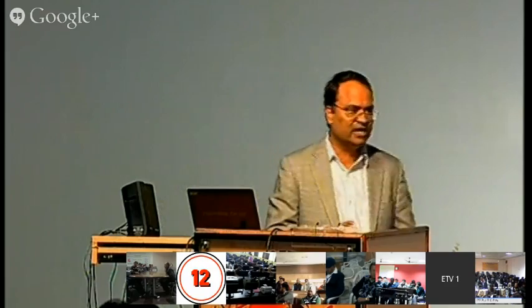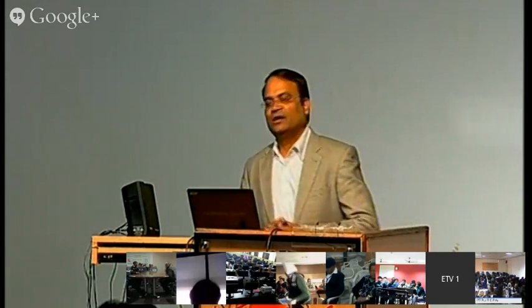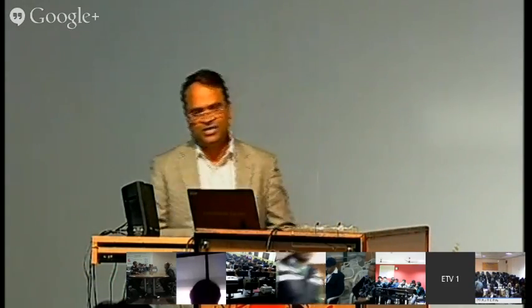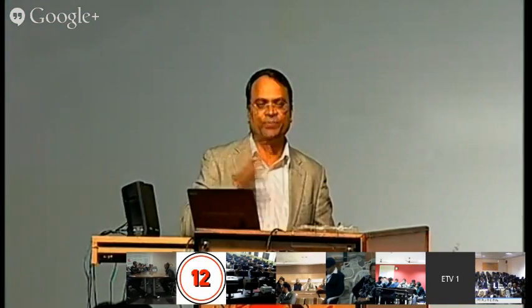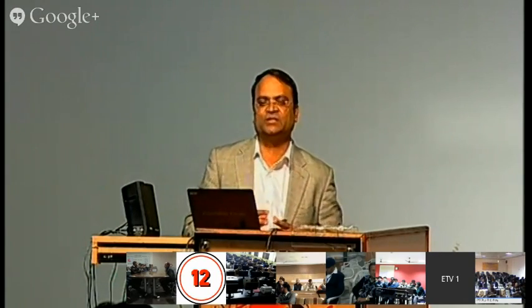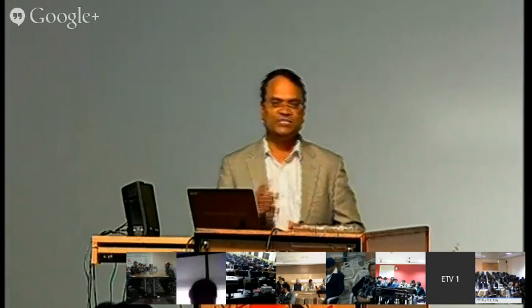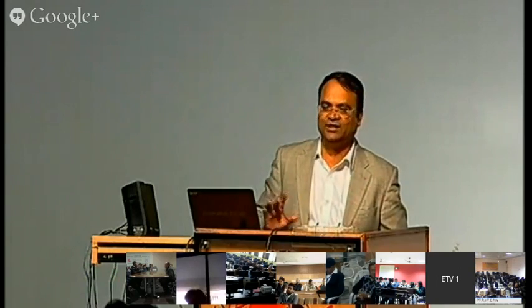So there are various types of designs. Right now, whatever I have discussed, single continuous surface profiles and biomimetic surfaces, copying them onto the surface. We try to copy those surfaces on the piston ring and measure film thickness and friction as well. I'll be sharing certain results.